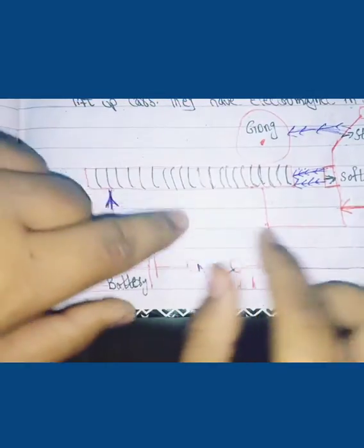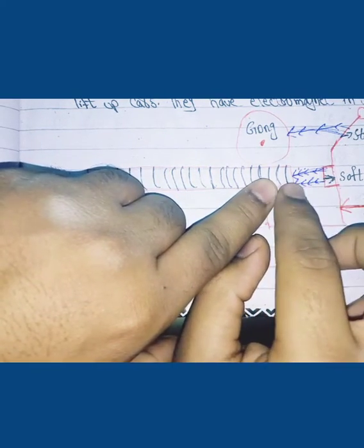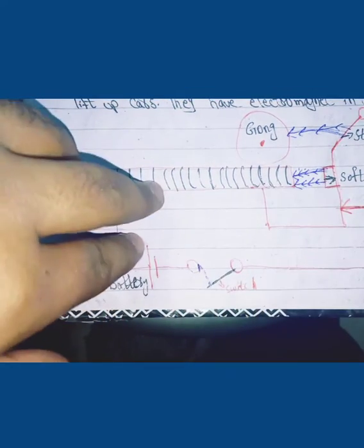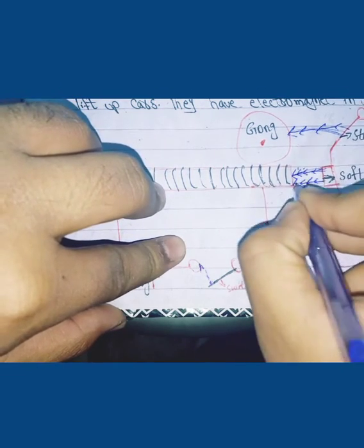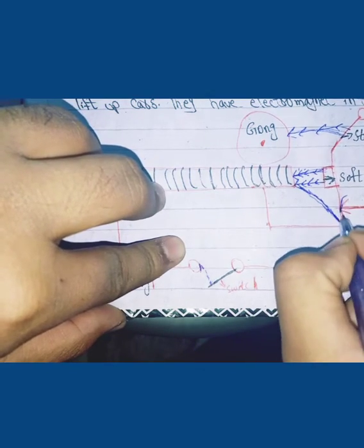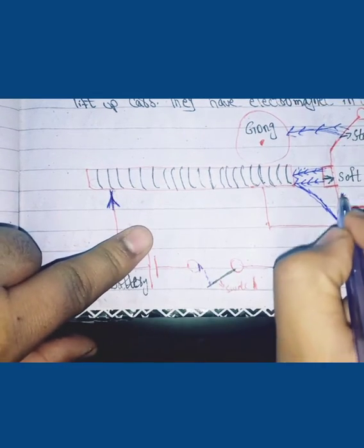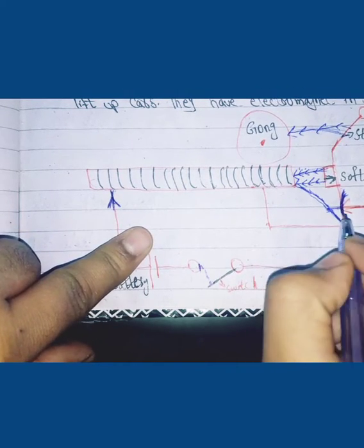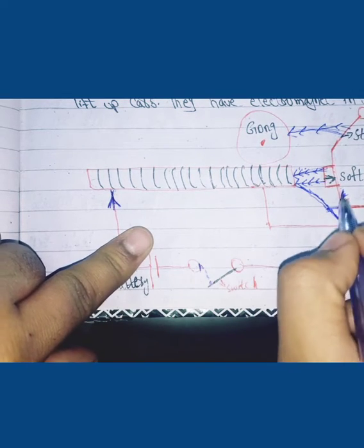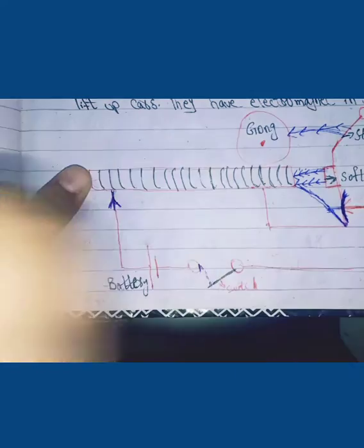Look. When the iron core travels towards this electromagnet, here it actually goes like this. So here it gets disconnected. Current is flowing through it, and there it got broken. The circuit got broken there. So current stops flowing through it. Whenever the current stops flowing through it, the electromagnet gets demagnetized.